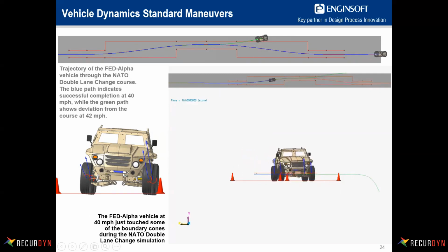This image at the middle left is showing the vehicle in the middle of some of the steering, and you can see, again, forces at the wheel center and torques, to provide some perspective. Of course, when the translational forces head towards zero, that means the tire is ready to lift off. In some vehicles, that can be a real issue. You can see here it's getting a little bit of sliding, and that's why it was getting so close to the cone.